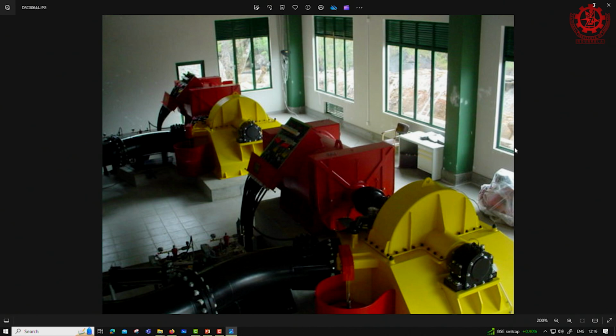Now, the utility circuit breaker trips due to a network malfunction, right. Something has happened on the network side and your breaker trips. Now, look here, water brings energy, you can't stop water instantaneously, right. Water brings energy and imparts it to the turbine, and the generator cannot take out the energy because the breaker is open. Now, there is a big mismatch. The only choice is for the rotating parts to overspeed and the kinetic energy to increase, and that will destroy the generator, right.